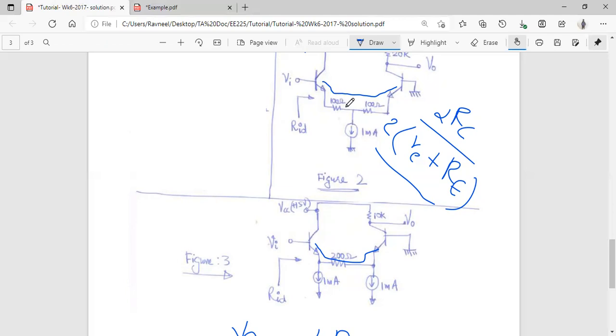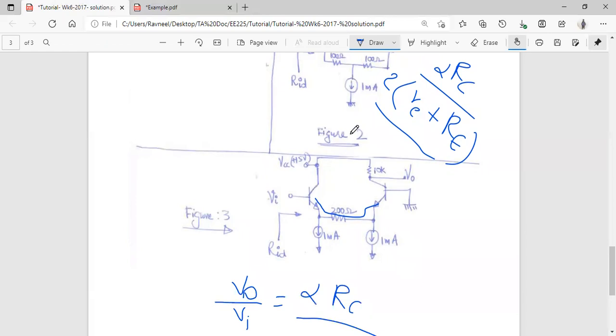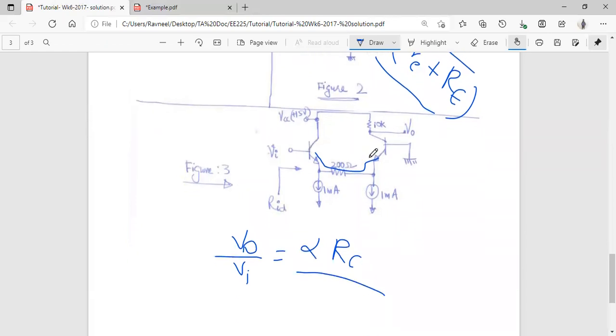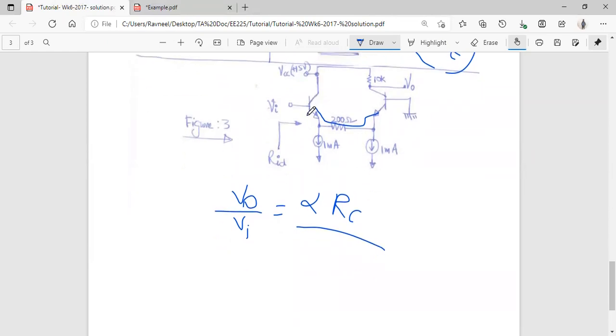So basically, whatever resistance we had, it was the sum of the resistance across this. The same thing is going to be done over here as well. That means we need to find the total resistance over here. In that case, it will be RE plus whatever resistance is being shared by both the transistors, that is 200, plus again the other RE. Since the transistors are identical in differential amplifiers, it is going to be RE plus 200 plus RE.